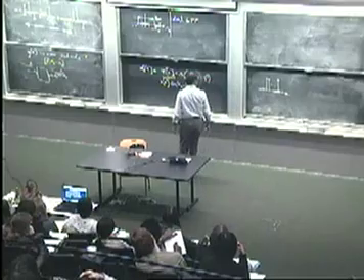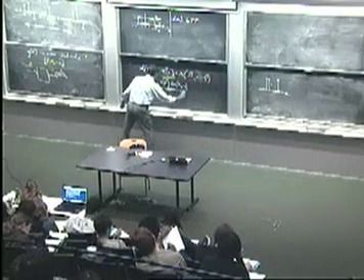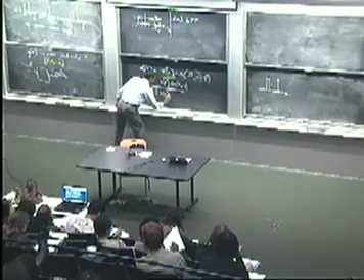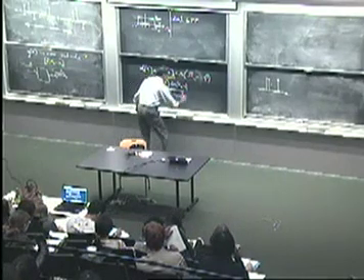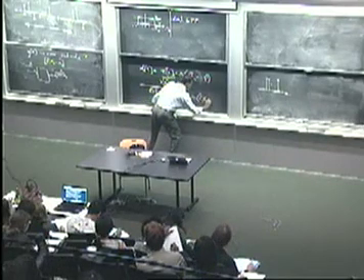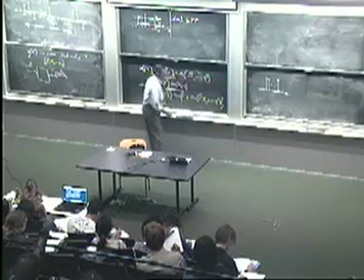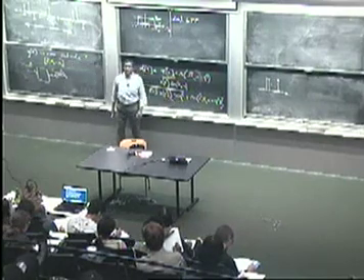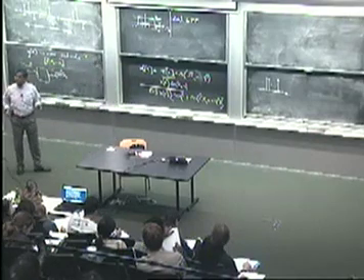So what we're going to get, I should write it down here, is 0.5 x of n, and then there are two pieces here. There's the cosine phi, and then there's the cosine of 2 omega c n minus phi. When you don't have any phase error, the cosine phi term is 1, but now it's reduced from that. The rest of the process is the same.